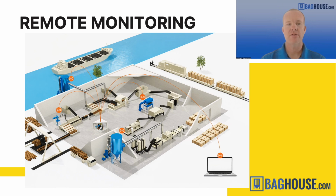So you can tie those into your central control system, if you have one, you can send this up to the cloud to generate reports regularly and alerts when something is going outside the limits, or we can even remotely monitor it for you and give you an alert when something needs to be addressed. For example, your differential pressure goes high, indicating that your filters need a change, or your fan vibration is trending high, indicating that the fan needs to be balanced, or maybe the bearings need to be swapped.